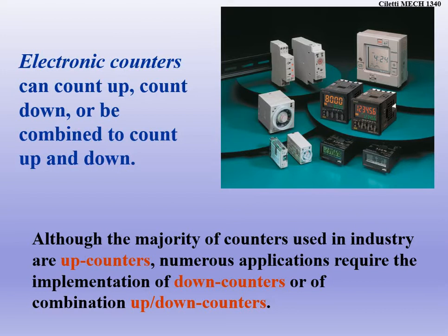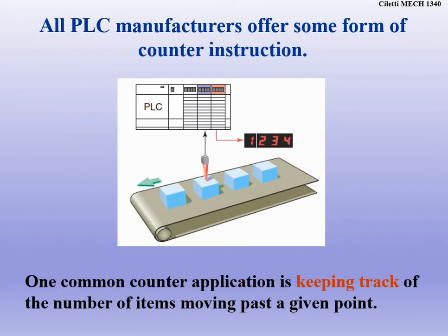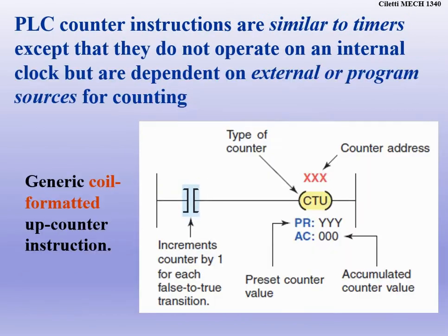And like I said, it doesn't matter if we're talking Siemens or Allen-Bradley. The concept of what we're doing is the same. In any form of manufacturing anywhere, there is usually some form of a counter. You want to keep track of your product. You want to keep track of how much product you're doing per hour, how much is going past a certain point. We go to Bridgestone, we see how many tires they're producing. They're keeping track of every single tire and counting. Same thing, we're counting cars as they run the line at Nissan.